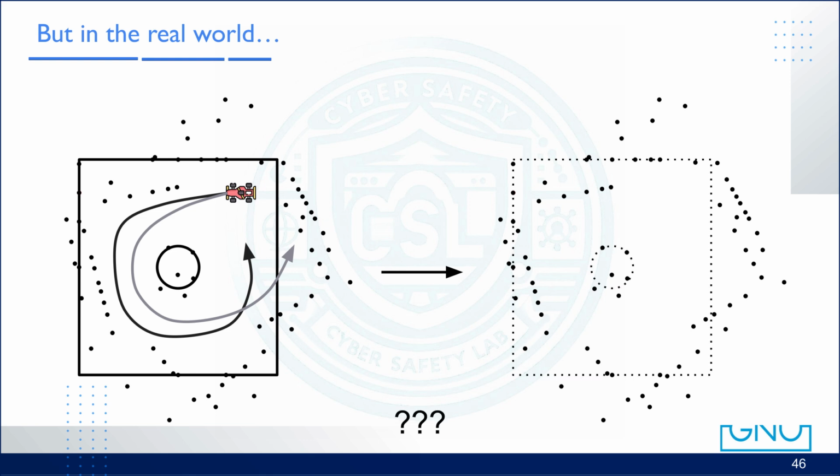As we continue driving, the errors in odometry keep accumulating, and the noisy LiDAR measurements are placed in the wrong positions. Eventually, the map we generate no longer resembles the real world at all. Everything drifts, the walls bend, the circular obstacle becomes distorted, and the entire map looks completely different from the ground truth. At this point, it becomes clear that simple mapping based on raw odometry and LiDAR is not enough. This is exactly why we need SLAM, a method that simultaneously estimates the robot's position and builds a consistent map of the environment.